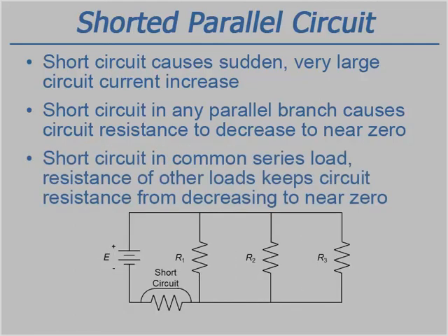If a series load in a parallel circuit becomes shorted, the resistance of the other parallel branch loads keeps the circuit resistance from dropping to near zero, which limits the amount of current increase due to the short circuit.